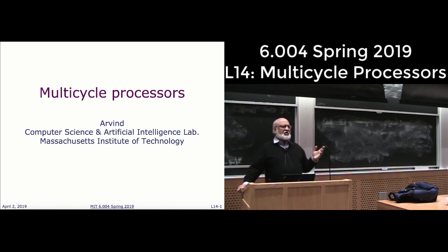And it's interesting because not all instructions will take the same number of cycles, or how to deal with these issues. And another very high level idea that you have to remember is the moment an instruction can't execute in one cycle, then you have to remember some data from one cycle to the next to continue the execution of the instruction. Okay, so that's what we'll be focusing on, multi-cycle processors.